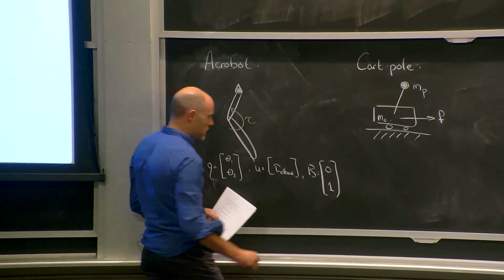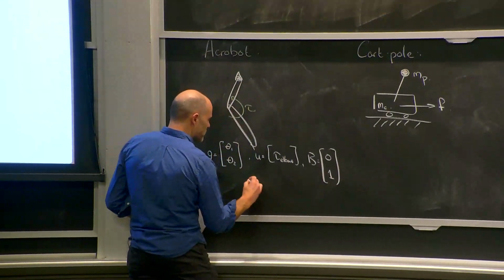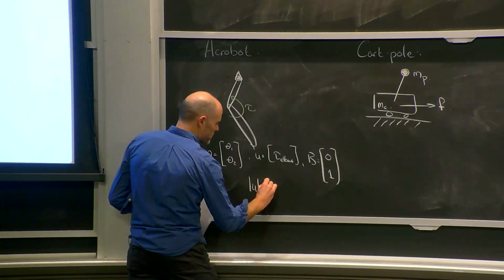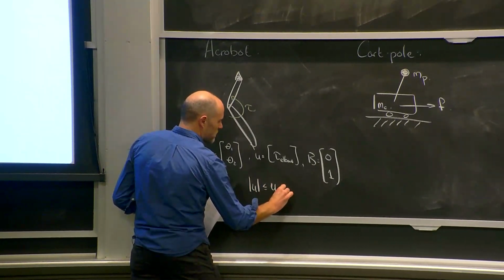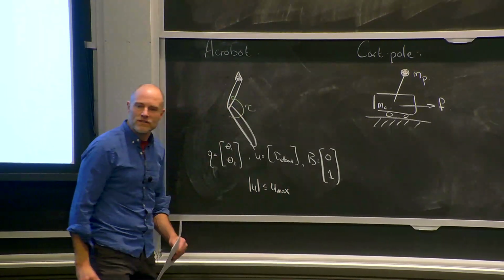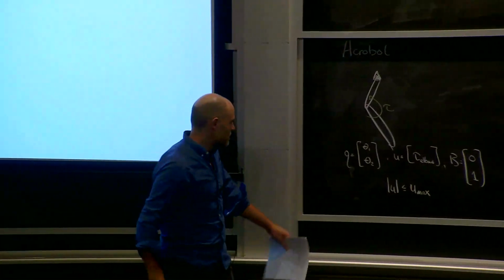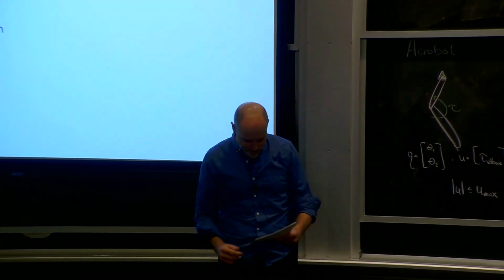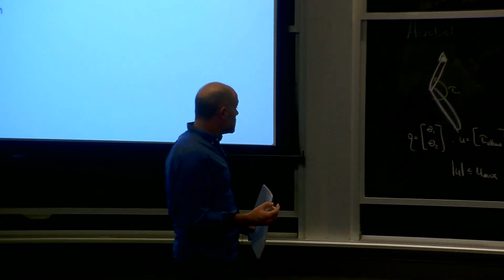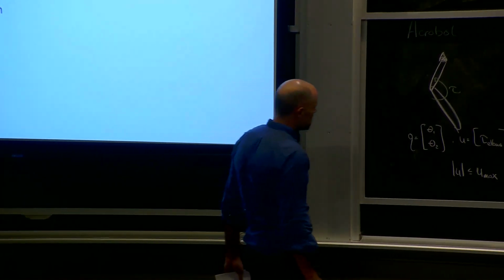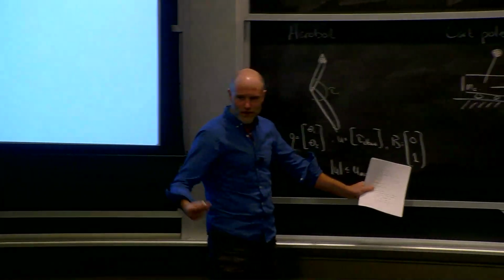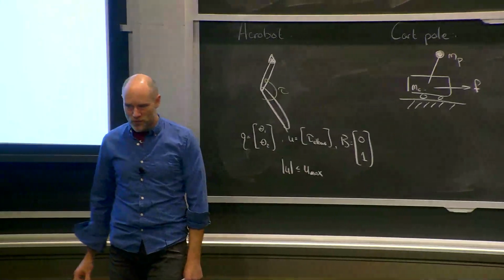Okay. And then typically you also have a torque limit, otherwise you can kind of cheat physics. If you have infinite bandwidth and infinite torque, then you can make it look like you're fully actuated. Okay, so unsurprisingly, it's underactuated, right? B is low rank.